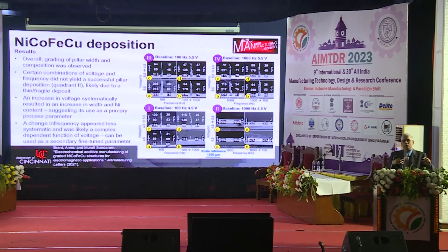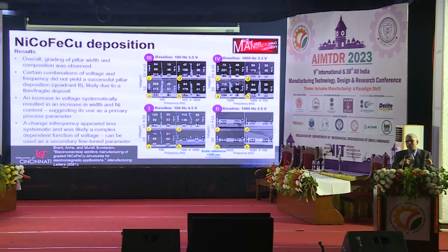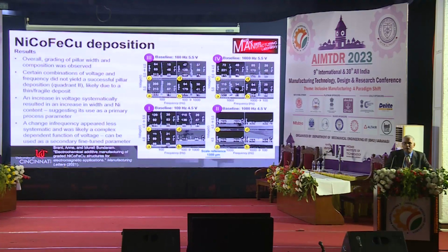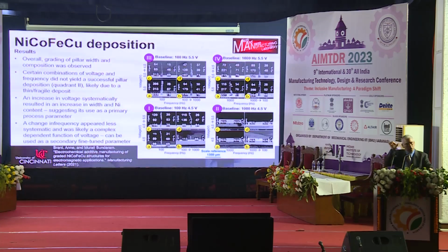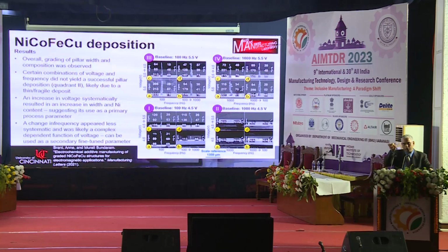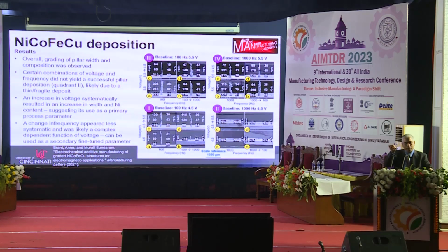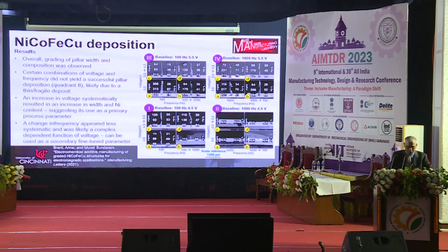So remember earlier I was talking about localization, how you will do that. Frequency is such a big deal. If you try to increase your pulse frequency, the deposit you get will become thinner and thinner. The problem is that if it becomes too thin, it will become very fragile, so it may break off easily. So there is an issue there. That's why I have this talk titled challenges and opportunities.